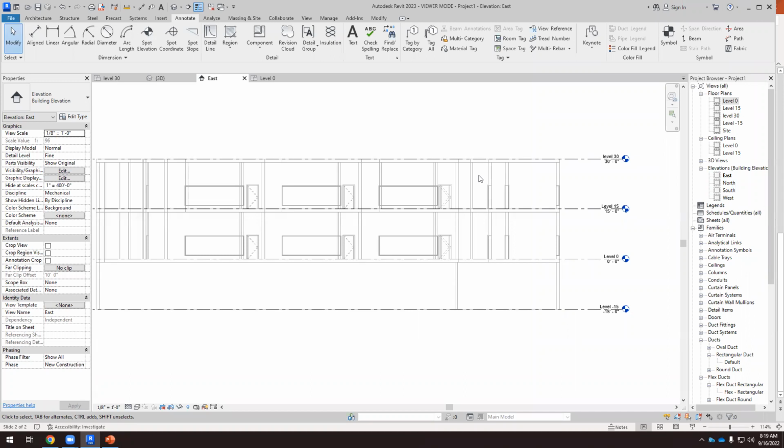So first, how can we do this? We have to place the air handling unit. This is because that affects the ductwork. So we will study the building, and then we will decide what the best place for the air handling unit is. And then we have to study where the vertical pipes are going to be.